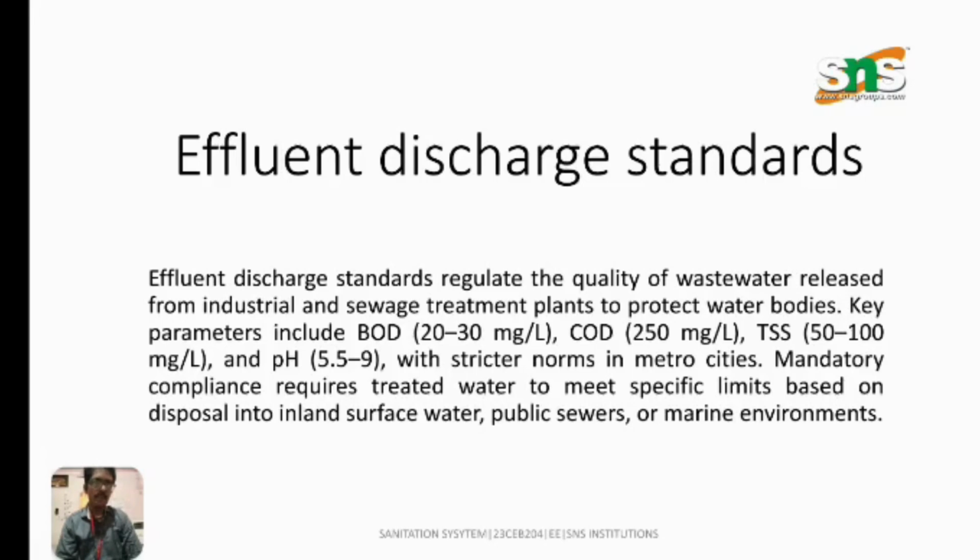Now I am going to present a topic on effluent discharge standards. Effluent discharge standards regulate the clarity and quality of the wastewater released from industrial and sewage treatment plants to protect the water bodies. Key parameters include BOD 20 to 30 milligram per liter, COD 250 milligram per liter, total suspended solids 50 to 100 milligram per liter, and pH 5.5 to 9, with strict norms in the metro cities. Mandatory compliance requires treated water to meet specific limits based on the disposal into inland surface water, public sewers, or marine environments.